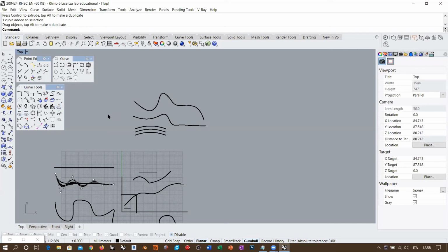Fair and fit, just to name them, allow, let's say, changing the topology of a curve, keeping the curvature normally under control. So fairing of a curve is very important, for example, when you want to make one geometry easier to manufacture, okay? Fair means making a geometry more gentle, more elegant, right?